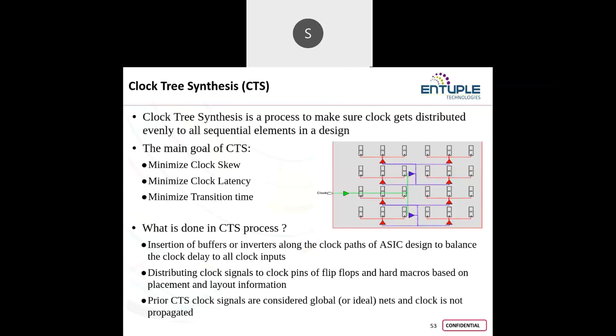When it comes to clock inverters, I use them because they provide a better balance between the rise and fall times. And also it helps me maintain the 50% duty cycle. Along with that, it helps me maintain the 50% of my duty cycle. So that's why we go with the clock inverter instead of the normal inverter.